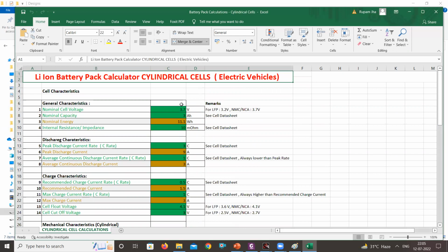So this efficiency of the powertrain, on which basis is it defined? What is the logic behind this 0.8? Is there any measurement? It is the efficiency of the powertrain, yes. It is how much power, how much current you are delivering, how much energy the powertrain takes in, as a ratio to how much it is consuming. Means there is an input and an output, no? Some of it gets consumed inside the motor. So the ratio gives the efficiency. There is a transmission loss actually. So that's what it is.